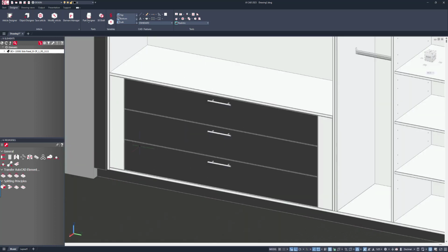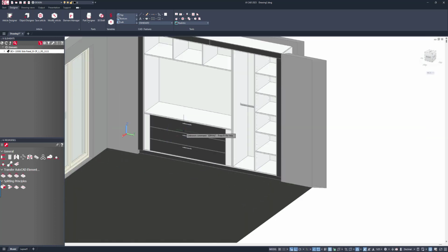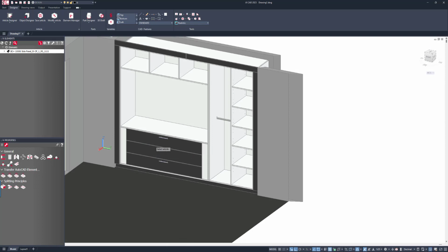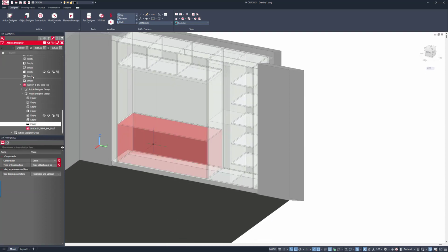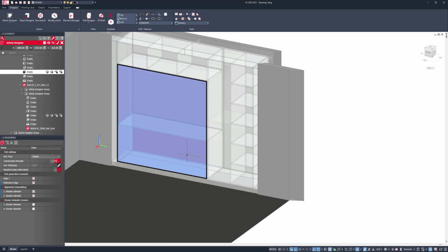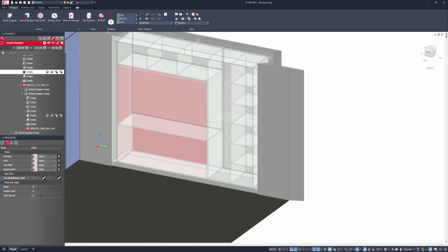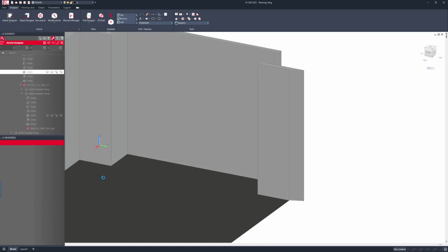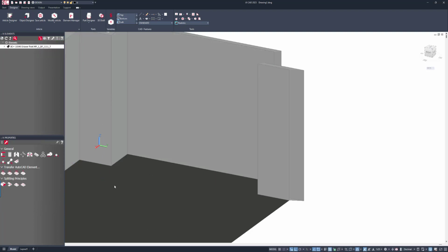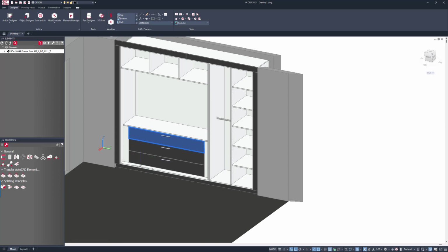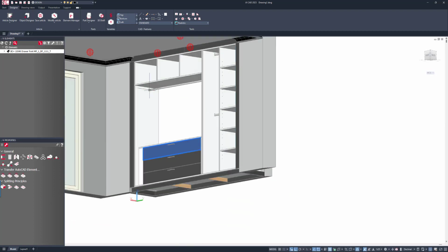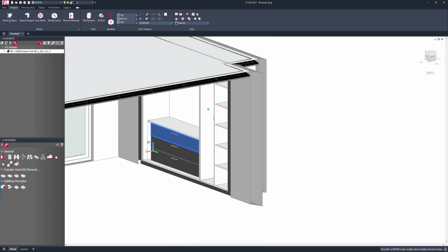I need to move that back because I want to put my doors on next. So let's go to that entire zone and go up a level. And you can see in here, I've now got the ability to go to the trims and do a zone reveal of 100mm. That'll push everything back. So again, if I just quickly click tick, you can see that that will shift everything back in here, but keep my initial depth for what I need.